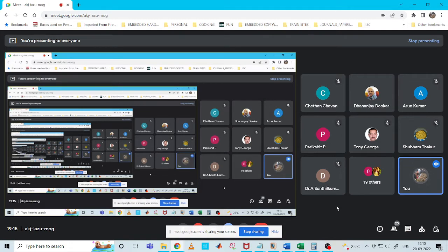And how are digital filters implemented? By using Z transform. Correct, but there are two forms of representation. One is the infinite impulse response, one is the finite impulse response. And then you have other structures also, like polyphase filter. But the basic idea is you have something in analog, you want to translate that to digital. So how do you do that?